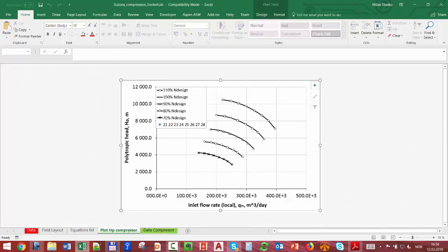It will be very small here, the RP. So I want to move it inside the map. For that I can use a choke. I can choke at the inlet of the compressor. So we have some tricks that we can use before changing the rate to move the point back inside the operational map.